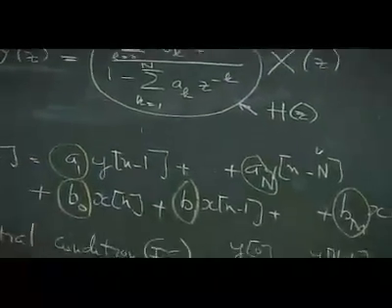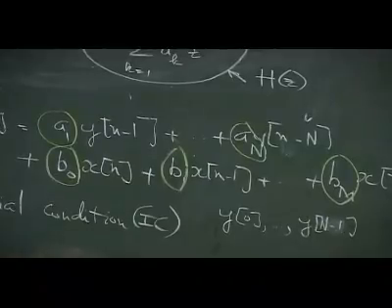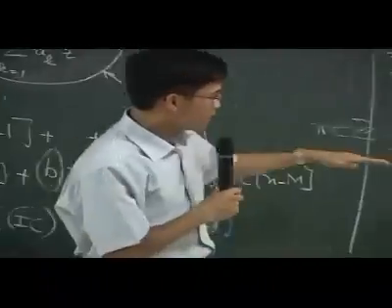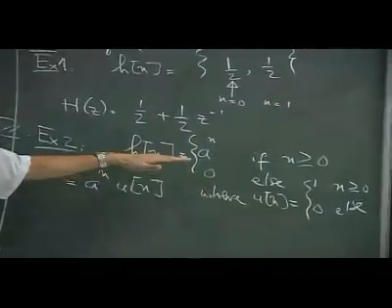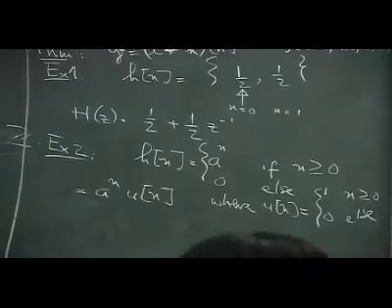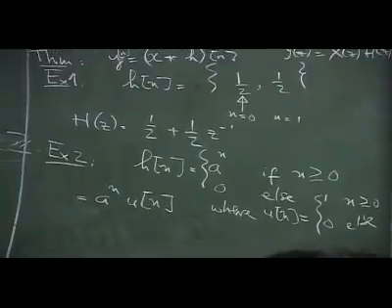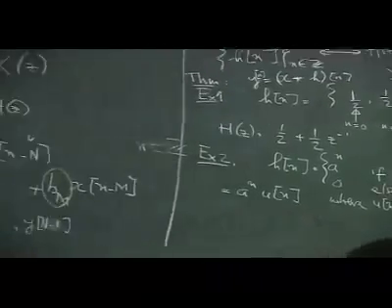It allowed me to compute a filtering operation with an infinite impulse response. This I cannot compute by the convolution operation, but I can do it using the difference equation, and this difference equation gives me this form.